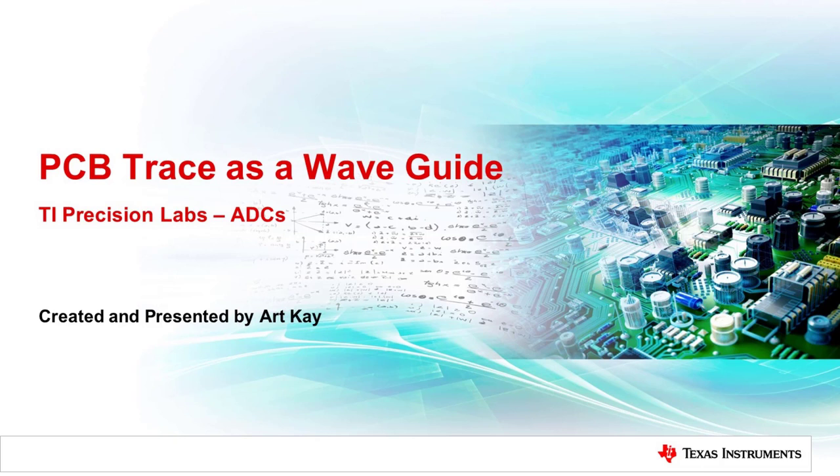This video looks at how return currents flow relative to the signal trace. The video describes the problem with ground plane discontinuities and also describes the best way to use vias to transition layers to minimize EMI. Let's get started by considering a PCB trace as a waveguide.